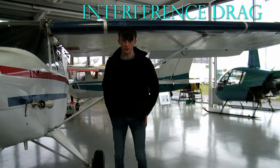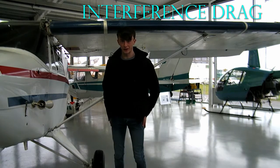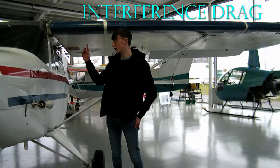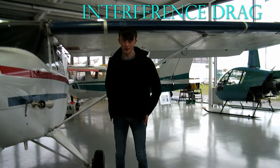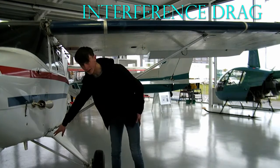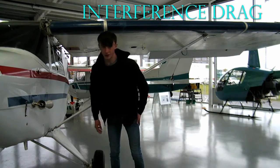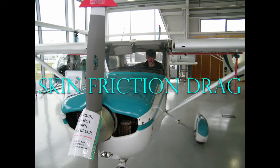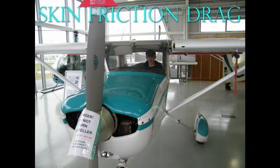Interference drag occurs when airflow around one object interferes with airflow around another, such as with the fuselage and the wing. Eddy currents and air turbulence are generated. As you can see here with this plane, fairings are used to reduce interference drag. Skin friction drag is the aerodynamic resistance due to the contact of moving air with the surface.